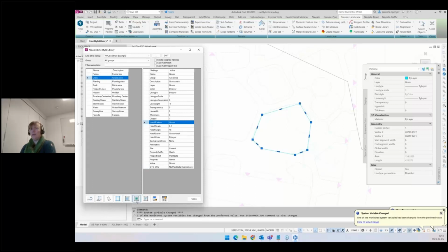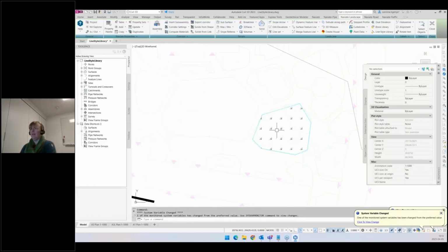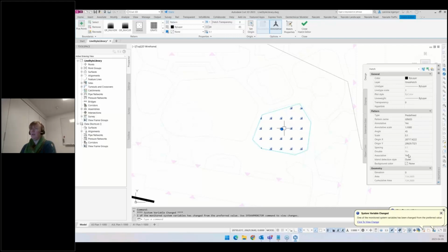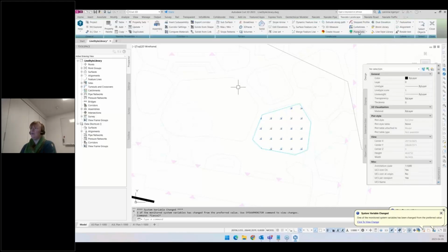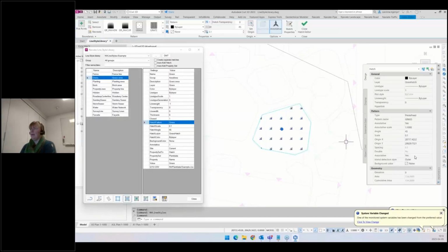Now these two commands down here are to create hatches. So now that I have my object selected, I can do hatch selected objects, and it's creating my hatch. And of course, it's giving me the exception again, but it's actually creating my hatch. It's creating the hatch on the layer that it's supposed to be, and it's using the information that I had in the dialog. So if I open it again, not the plant data, it's the wrong command. So let's just close that one and go to Line Style Library, which is what I'm talking about right now. We can see the information here about my hatches that I'm doing. So I can create the hatch as well.